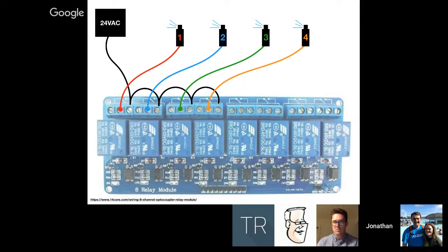So what we're saying is that currently, over here on the right, we've got a jumper between VCC, which is the power to all these pins from the Raspberry Pi, and that just uses the same power to actually hold the gate open or closed. Yeah, but if you switch it to the other one, you'll actually have to run a line from the 5-volt out on the Pi into the VCC pin on the relay, and that's what it will actually send to the relays.